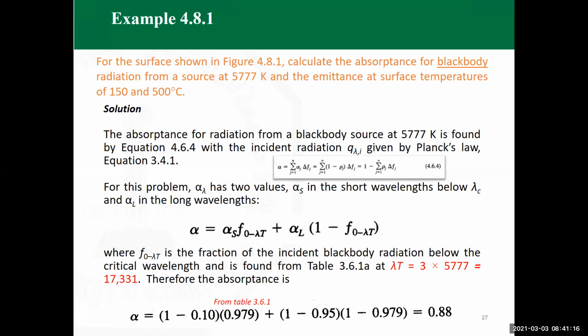And what it will not absorb, what it will be reflecting, or the losses here, are going to be 12%. Are we going to lose this all? That's another story, because this quantity that is going to be emitted is going to be coming from what we call a low temperature surface, and we have a glazing, we have glass on the top, and glass is opaque. This is the greenhouse effect that we talked about in the introduction to the course.